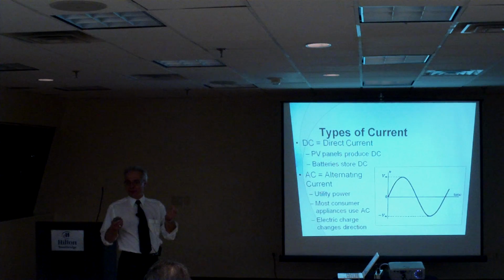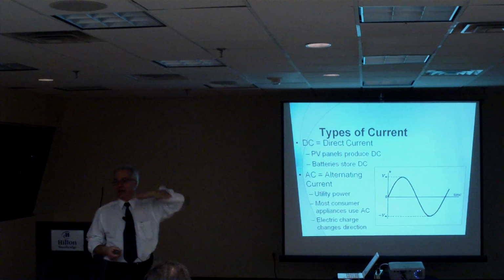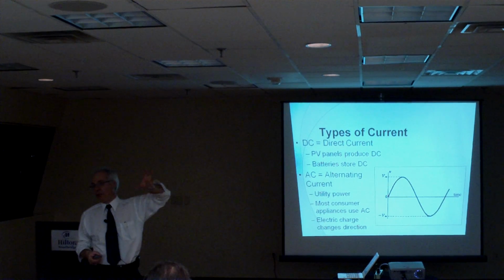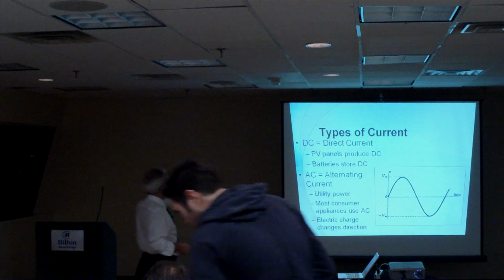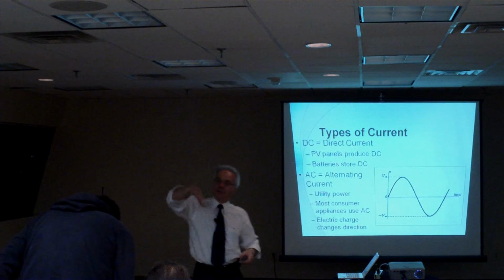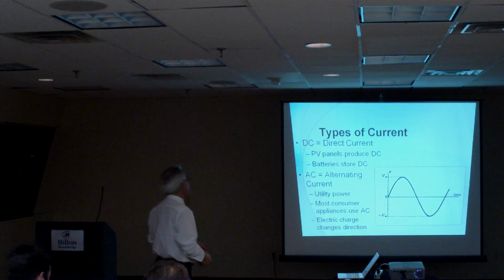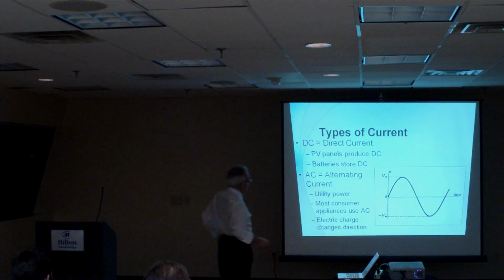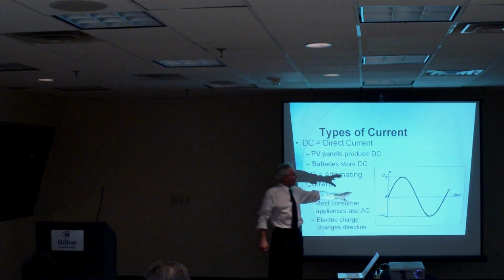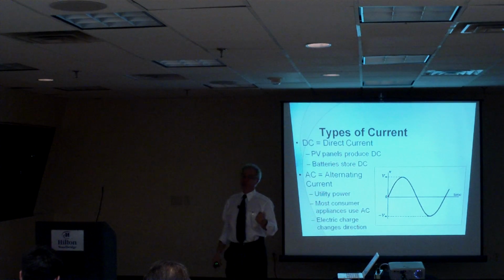You put the probes in the appropriate position, you put the selector switch to DC, and you're measuring a level of value, of voltage and so forth. When you measure AC, obviously you know that AC fluctuates over a period of time. So obviously you cannot capture this waveform at any point in time. So you don't know whether you're capturing the peak or the negative peak. So you're measuring something that's called what?